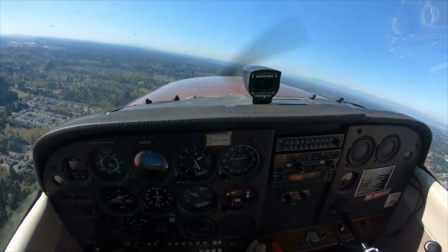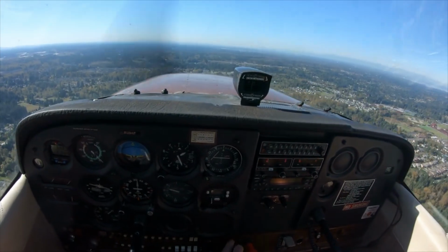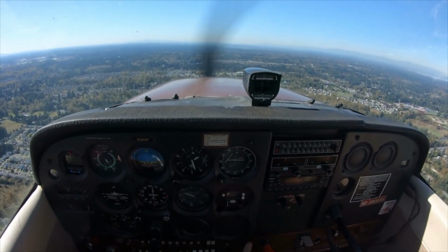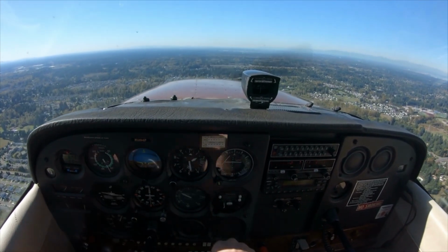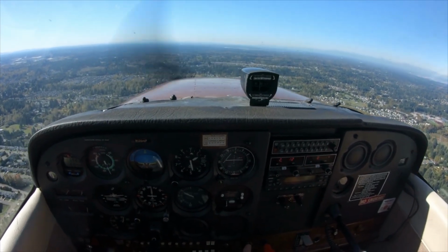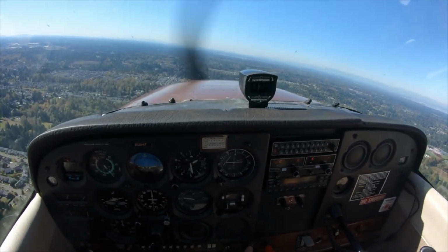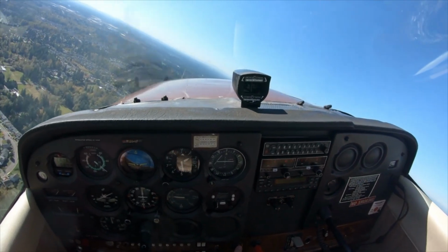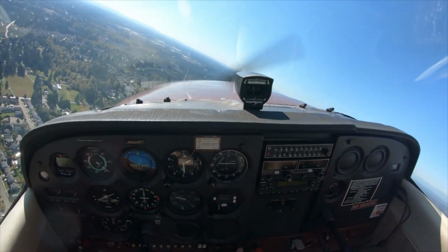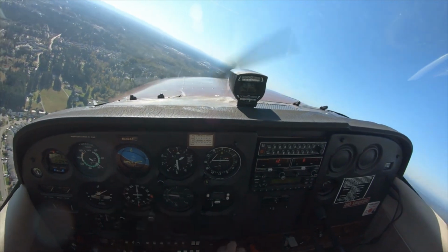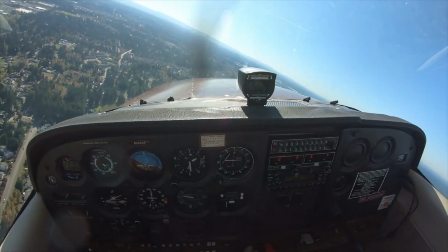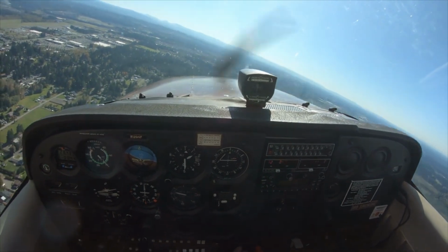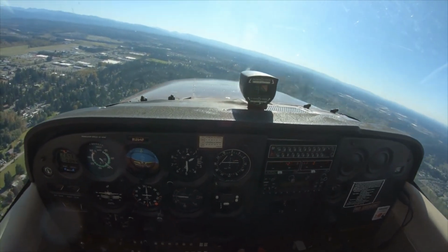After the landing gear has been extended, if applicable, or when beginning a suitable final approach, the pilot simultaneously adjusts the power and the pitch attitude to establish and maintain the proper descent angle and airspeed. During a stabilized approach, small changes in the airplane's pitch attitude and power setting are needed when making corrections to the angle of descent and airspeed. The short field approach and landing is an accuracy approach to an aiming point. The procedures previously outlined in this section on the stabilized approach concept are used.